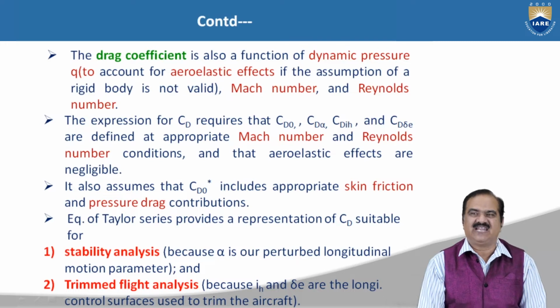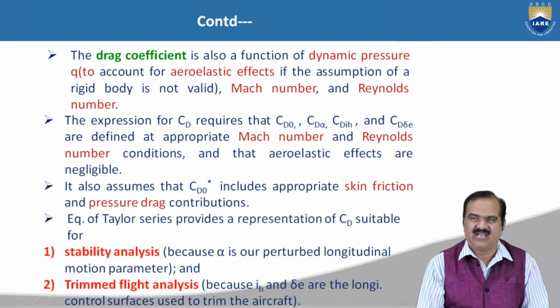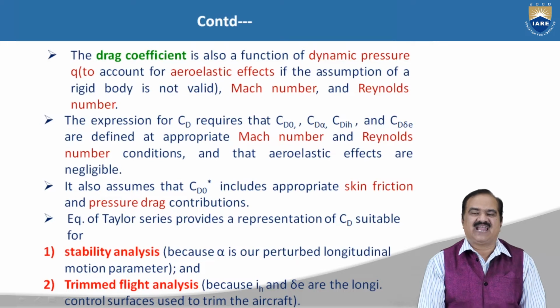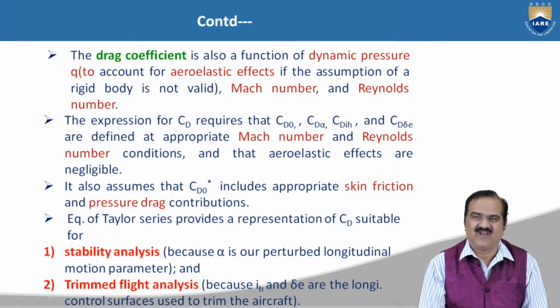So we are considering that aeroelastic effect is negligible. It also assumes that CD naught star includes appropriate skin friction and pressure drag contribution. So this CD naught star is CD naught plus the other factors which are to be considered.